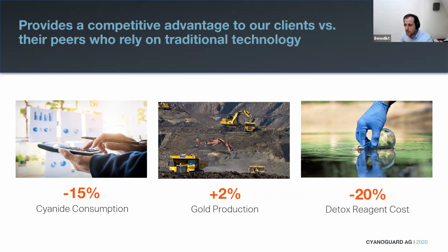As a consequence, the excess cyanide in the tailings is reduced, leading to lower or even zero detoxification costs, depending on the detoxification process and the situation of the mine. What's more, in a couple of instances, we have been able to identify cyanide under-delivery in real time in the process. That information, available in real time, helped the mine to redose the cyanide and optimize the recovery rate of gold that would have normally been lost to the tailings.